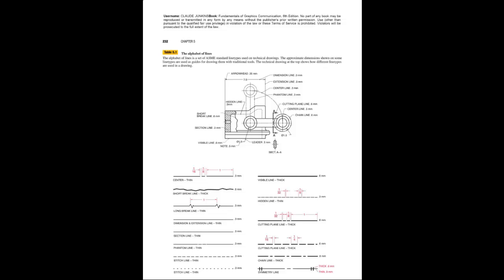When we look at this drawing, we can tell what's physical. This armature is shown with this center line that says it can pivot 90 degrees vertically, and it shows us this phantom line or ghost line that says this is what it would look like when it's vertical. It gives us dimensions. It gives us this cut line. Notice how dark this is. This is a 0.6 millimeter, and I might even go a little darker than that on a section line.